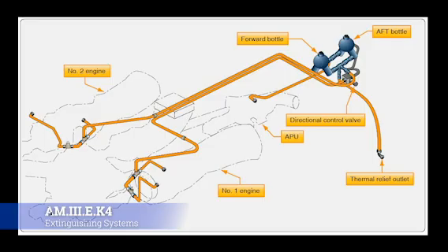Typically this is going to have what we'll call a fire bottle, or a discharge bottle. You'll hear them referred to a little bit differently depending on the aircraft and the context in which you're working, but they're all basically the same thing. They're a pack of super pressurized fire extinguishing agent, and you flip a switch and it discharges all of that agent into the engine or onto the engine, depending on where it's at.